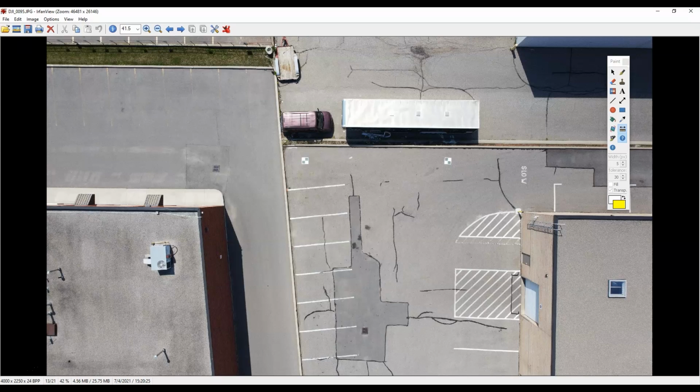So, if you're georeferencing something, or if you're going to be using different types of targets, it just goes to show you that depending on the size of your target, or how well you can discern where it is, this is important information to know and a good test to use with your specific drone and the specific lens that you have. Okay, well, that's it for the images.